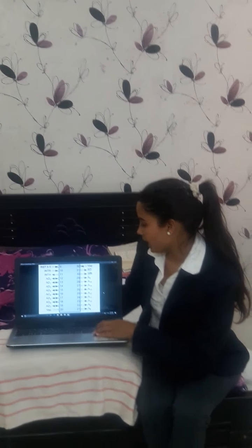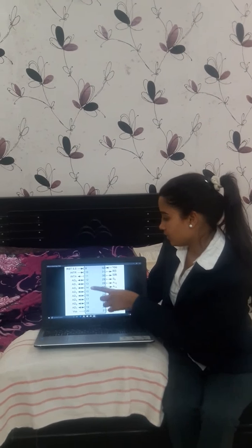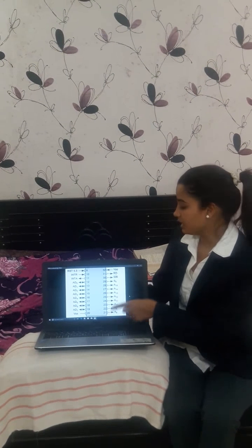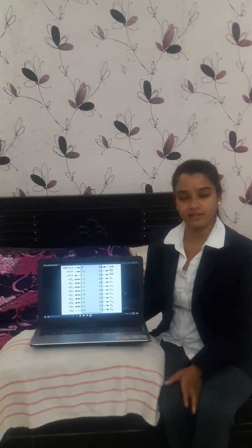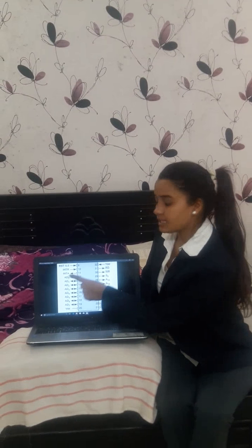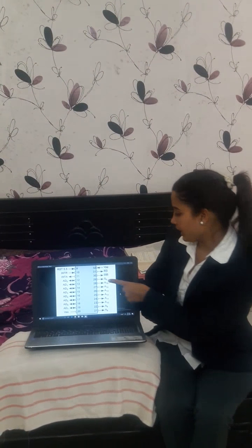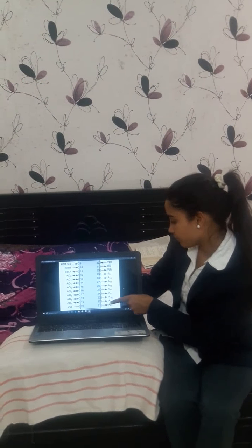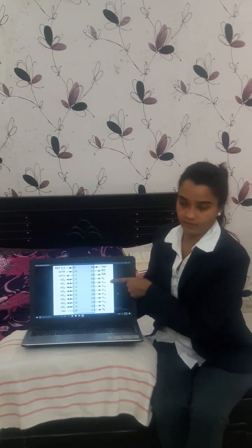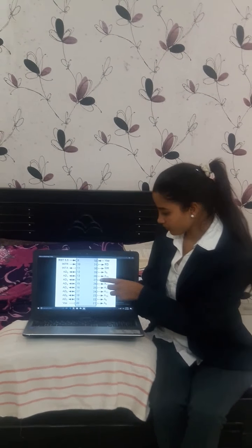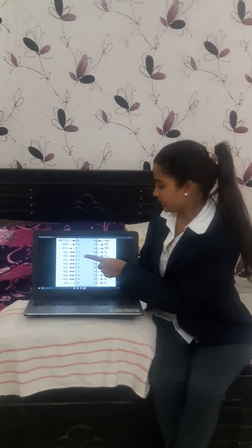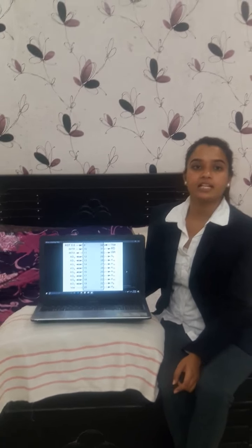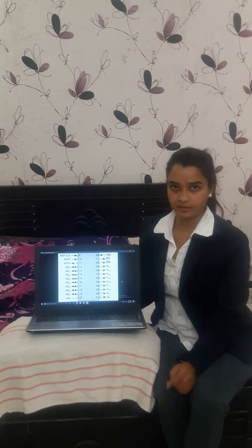Next pins are from 12 to 28. These include the external data bus as well as the external address bus, namely AD0 to AD7, A8 to A15, except pin 20, which is the voltage pin. The lower address pins, that is AD0 to AD7, are multiplexed with data here.